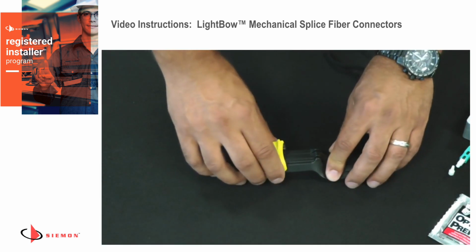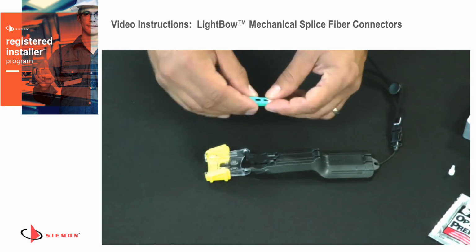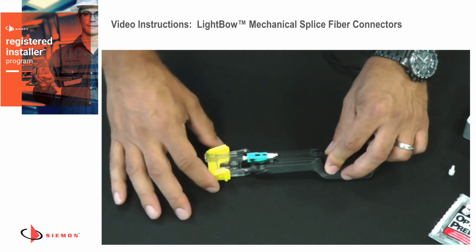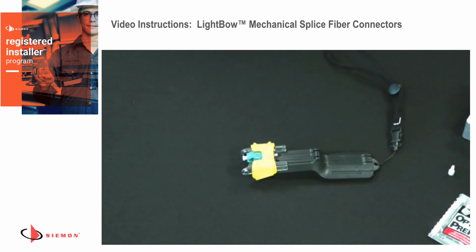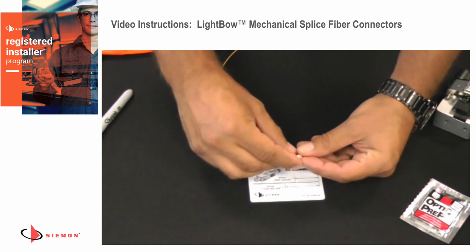To begin, open the tool and select the connector. In this case, it's an SC connector. Place it into the SC pocket in the tool. Close the lid, press firmly until an audible click is heard, and then slip the lock collar forward. Place the boot on the 900 micron fiber and pull it back out of the way.